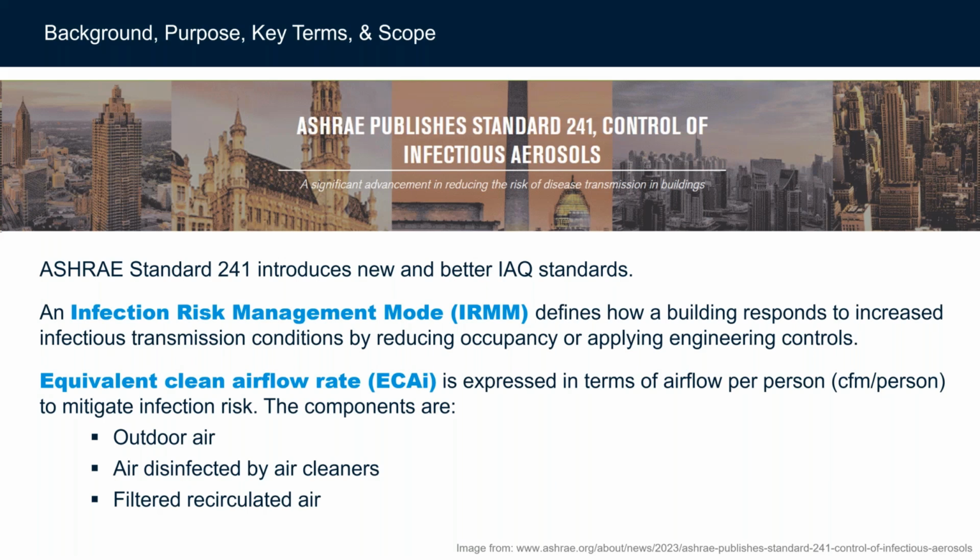And as part of that, they've introduced a term that they call the equivalent clean airflow rate. And I'll get into it, but it's really designed for CFM per person. And so they give you this ability now to calculate every type of added feature within that breathable zone, get some sort of calculation so that you can then determine does it meet the summation of what you need for the equivalent clean airflow rate.